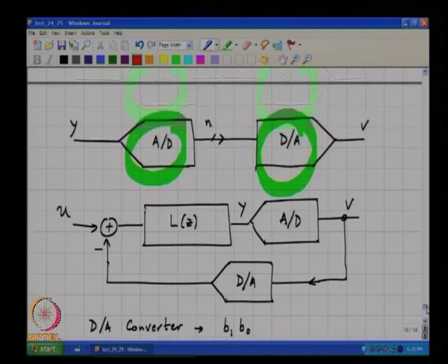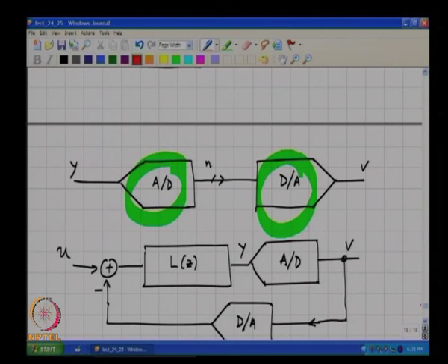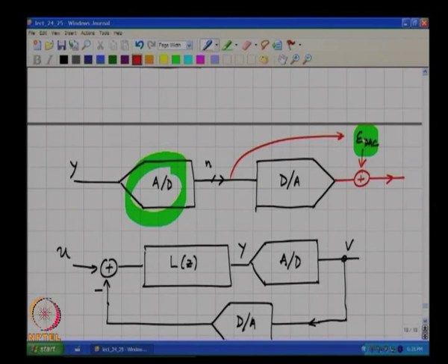Yeah, okay. So, what he is suggesting is that you can think of a non-ideal D to A converter, where the levels are not what you expected, as an ideal D to A converter plus some error sequence EDAC, right, where clearly this EDAC depends on code.